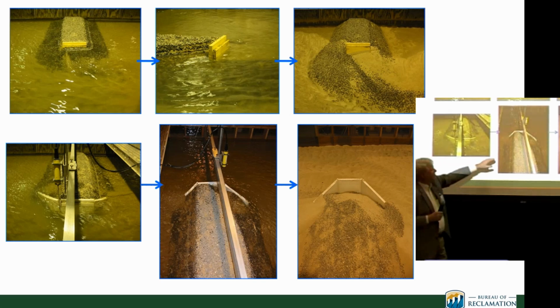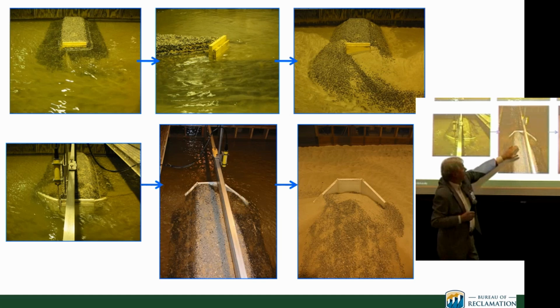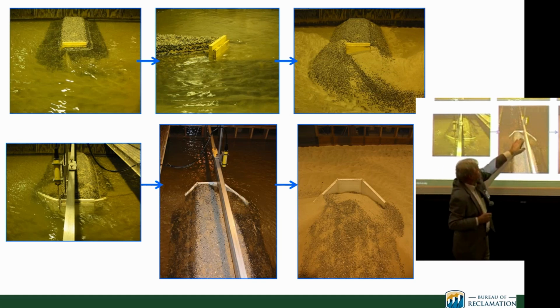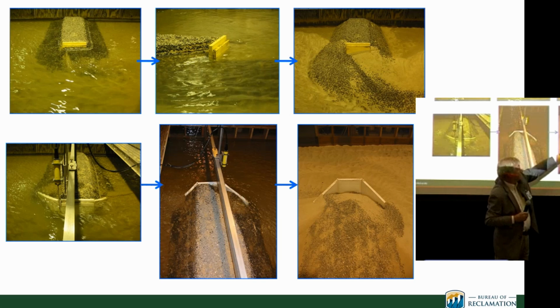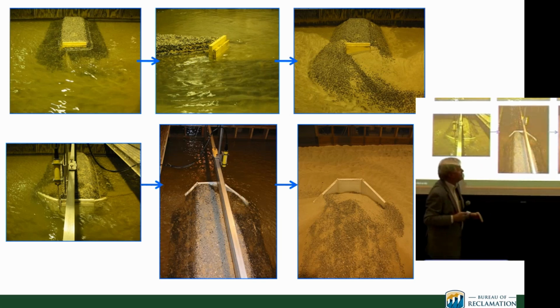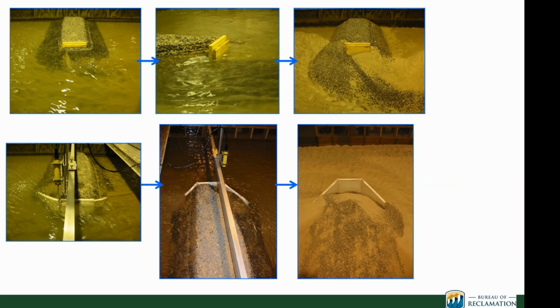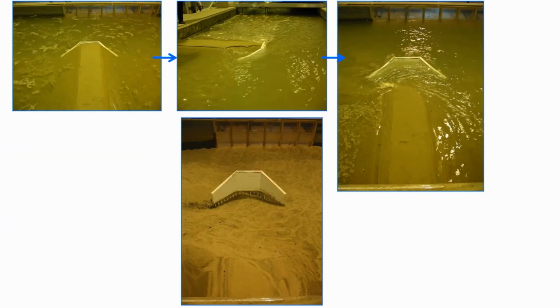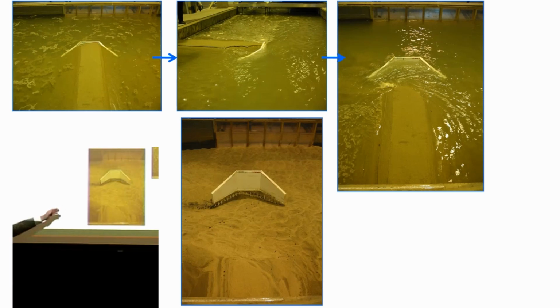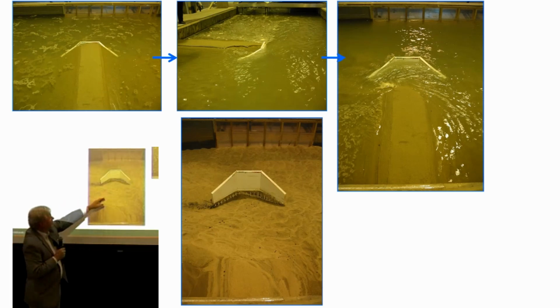Here you have an encroachment of flow behind the wing wall, and this particular experiment ended in that situation. Wing walls can be supported by piles or circular piles or H piles or sheet piles. Sheet piles are problematic because they create a rigid structure at depth. They're cheaper. So this is another experiment where we have an erodible embankment and you see breaching of the embankment and you get a condition like this. So the abutment is out here, the earthfill approach is here. So modeling the earthfill approach is quite a challenge.